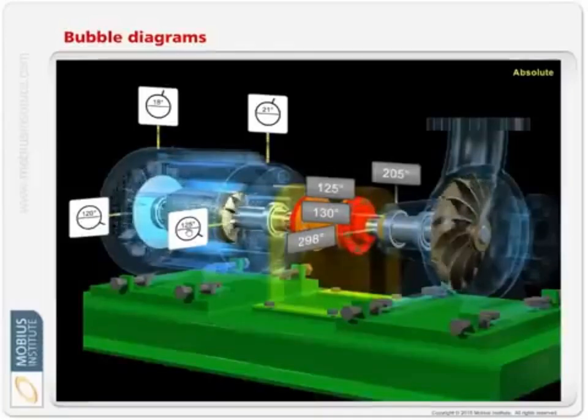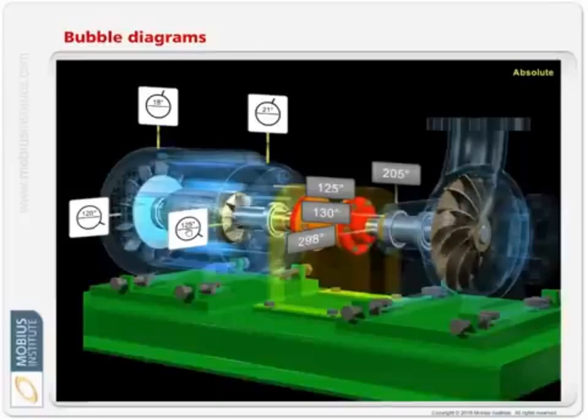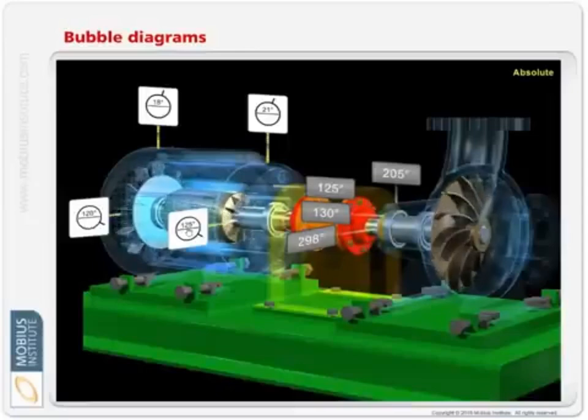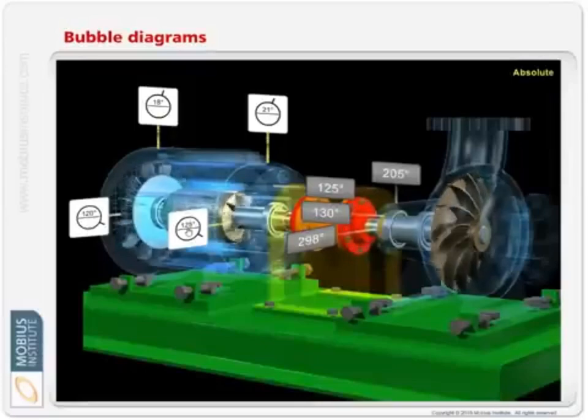So now we have another weapon at our disposal. We can use the spectrum, which gives us an indication of the fault condition and the severity. The time waveform provides extra detail, and in certain circumstances it provides really important detail.